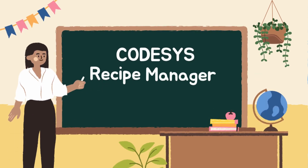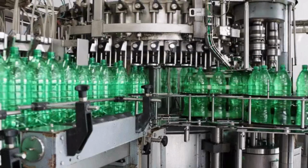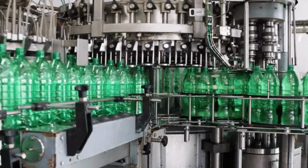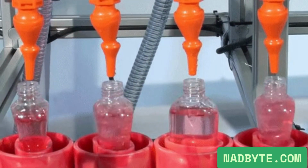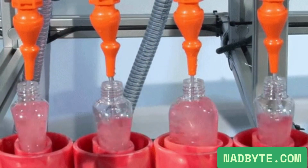Today, we're diving into an essential and incredibly useful feature in CODESYS, the Recipe Manager. Let's take a real-time example to understand recipe management more clearly. Imagine you're working with a Sprite bottle filling machine on a beverage production line. In this setup, the machine needs to handle different product types and bottle sizes efficiently. Instead of manually changing settings every time you switch products, you can use recipes to store and recall predefined parameters.